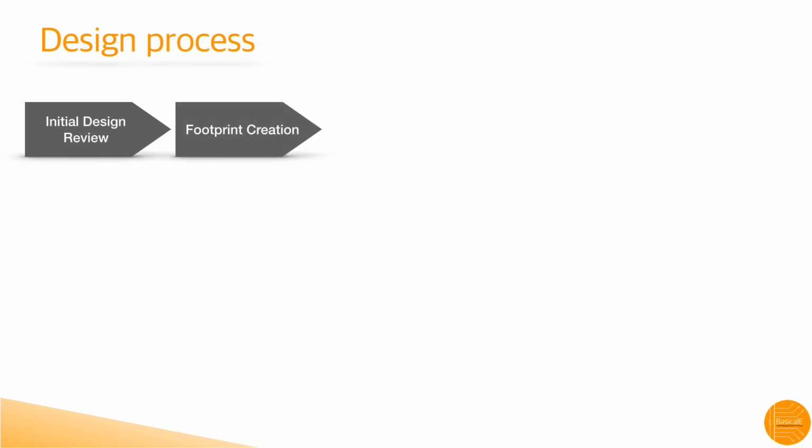Step 2 is footprint creation. Create footprints and pad stacks of components as per the manufacturer's specifications and library standards. Those are the fundamental building blocks of PCB. And then it is reviewed and stored into a parts database.